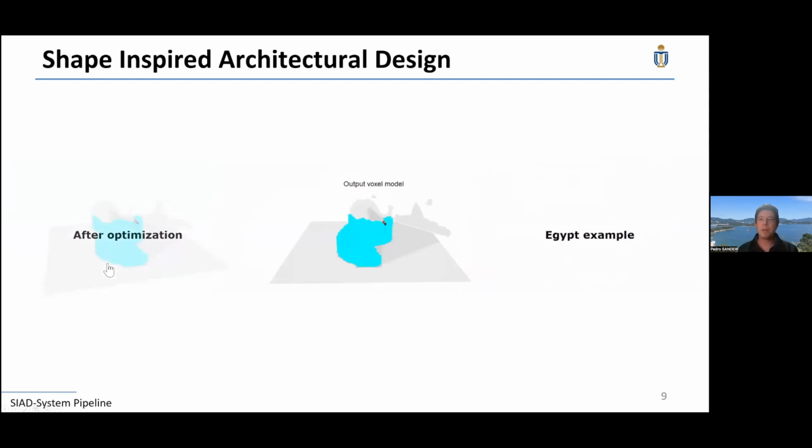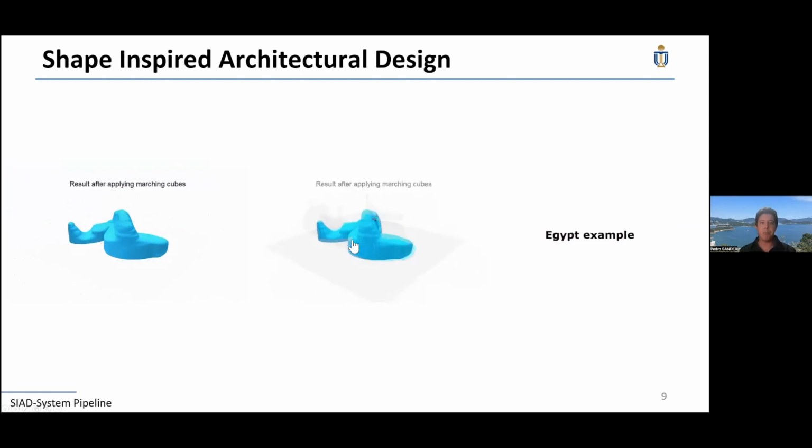Okay, so this is basically the result after the optimization. You can see that the optimal ground views are not orthogonal anymore there. The user can actually constrain the view ranges based on where they want the model to be, okay? Then we make a voxel model based on the final camera and image parameters that we have. And we will later talk about converting this into a mesh model, right? And that's what we do here, but we'll discuss it later in a little bit more detail.